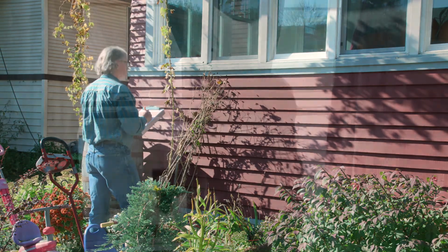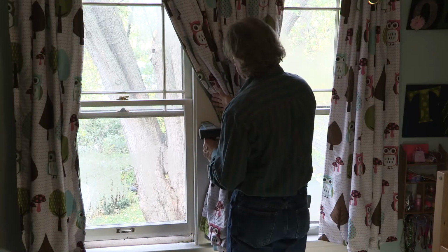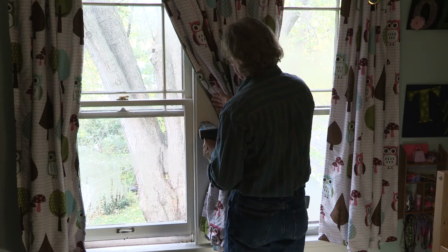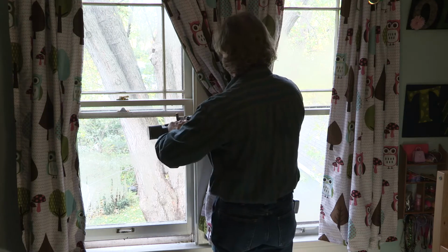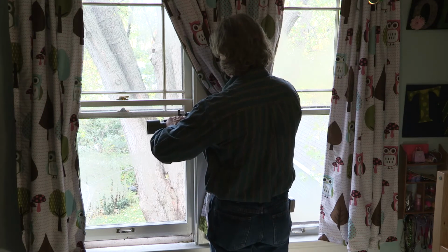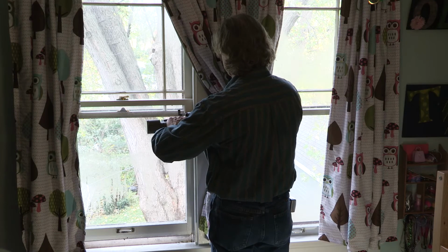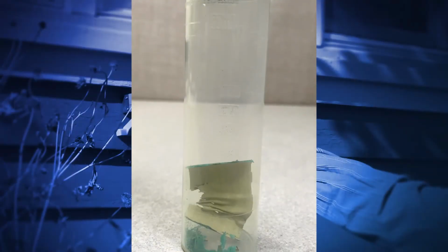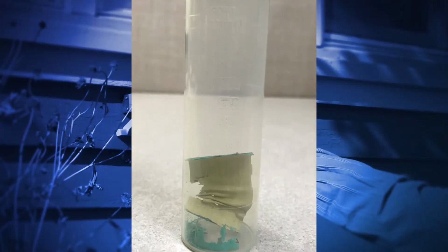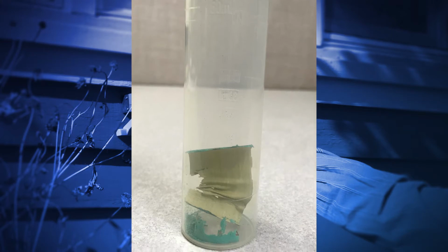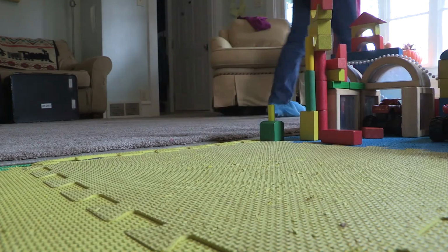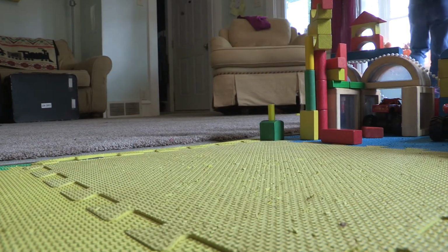Continue to test all other like surfaces and testing combinations in each room equivalent with deteriorated paint. You may not presume lead-based paint is not present on a surface. Paint chip samples are required to verify all inconclusive readings from an XRF, or you must presume that there is lead-based paint. Document each individual XRF reading in your field notes.